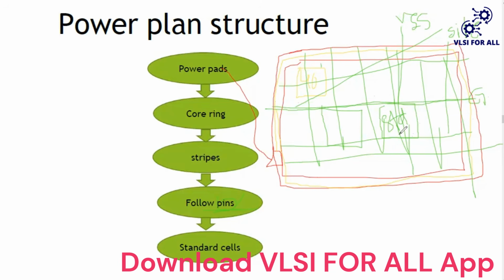Next, the standard cell side rows will have the VDD or VCC. Both are the same. VDD and VCC are the same, for power purpose only. We can consider them as VDD and VSS; the names will be different. If a single domain is there, VDD is the single name. If multi power is there, VDD is one power domain and VCC is another power domain.